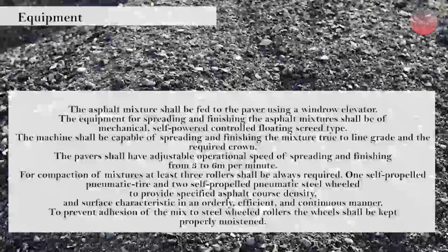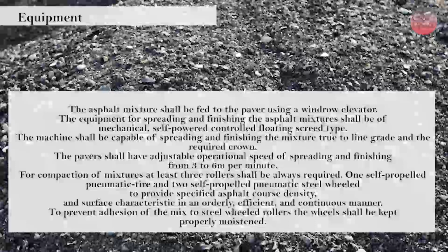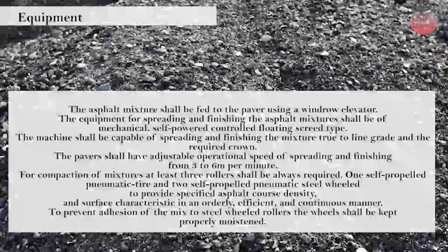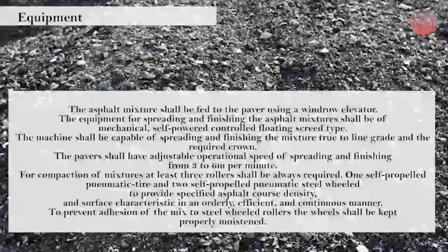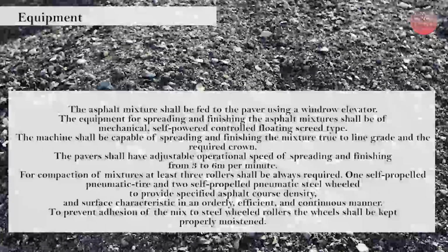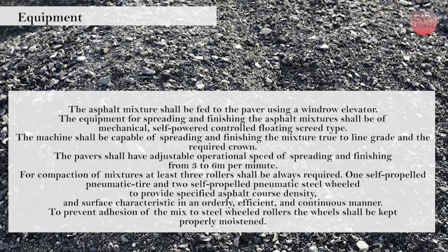Equipment. The asphalt mixture shall be fed to the paver using a windrow elevator. The equipment for spreading and finishing the asphalt mixture shall be of mechanical, self-powered, controlled, floating screed type.